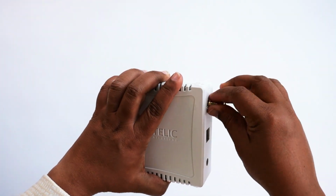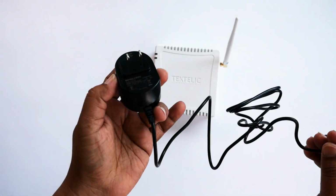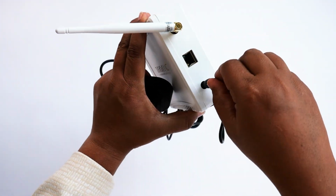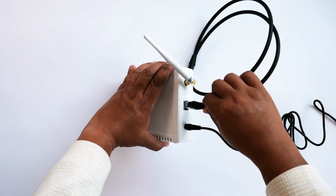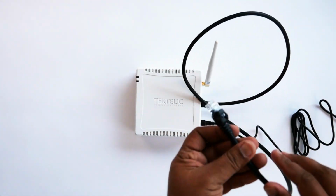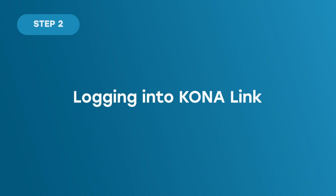First, I'll attach the antenna. Then connect the power cable. Then connect one end of Ethernet cable to the gateway, the other end connected to the LAN. Now we're ready for configuration.